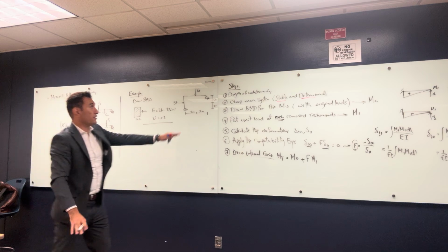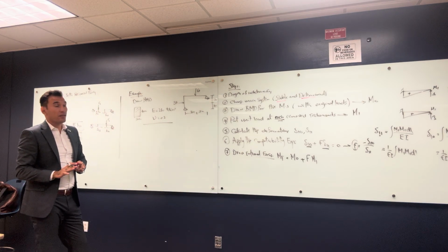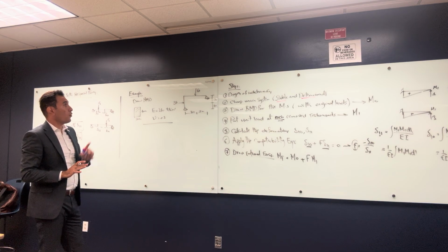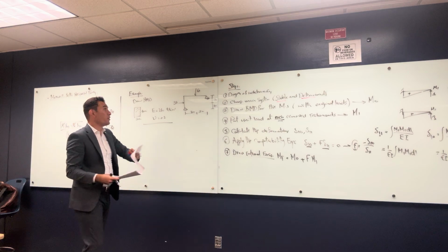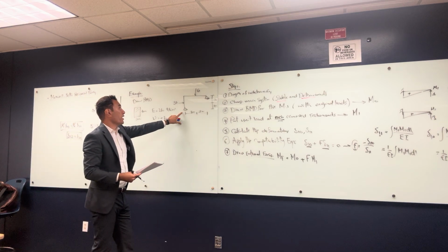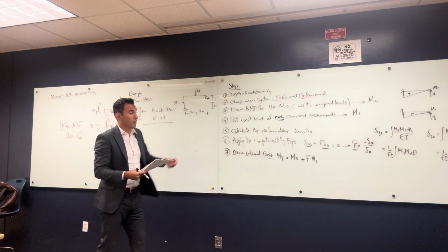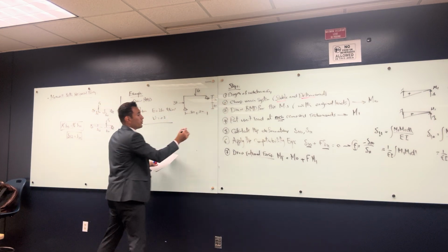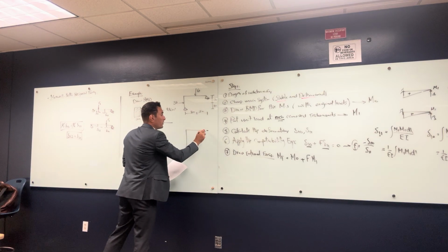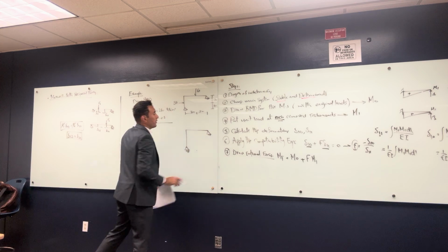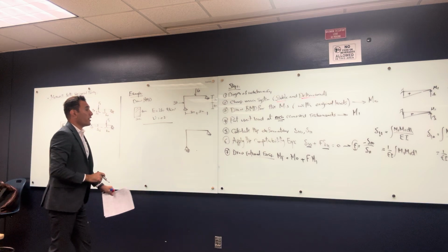You guys tell me step by step what I'm gonna do. Degree of indeterminacy, right? What is the degree of indeterminacy here? 1, right? So I can pick a main system of my own choice. You can make this a roller, and you can make this a roller. Not both of them roller. If both of them are rollers, it's gonna be on a table, right? So one of them should be a roller. I choose here that this be the roller. By the way, if you choose this one, it's still right. I mean, just this one, but this one stays hinged. Okay, just pick one.